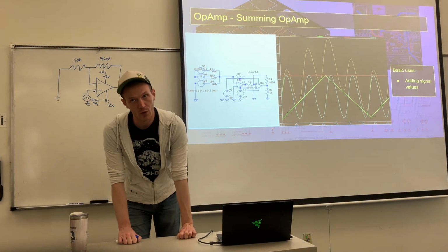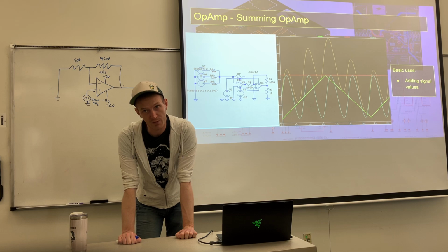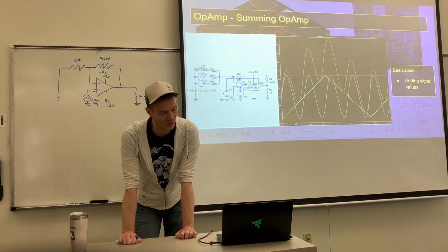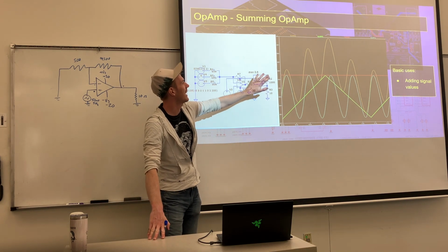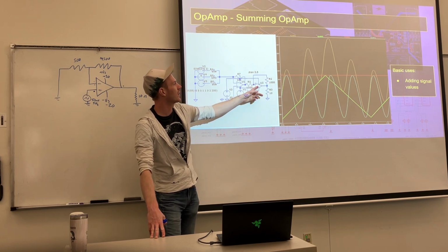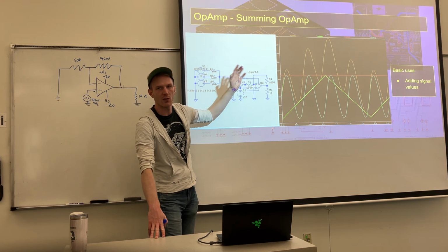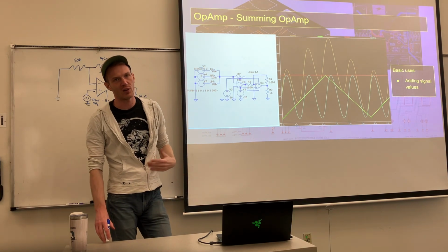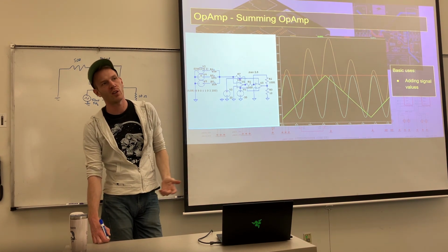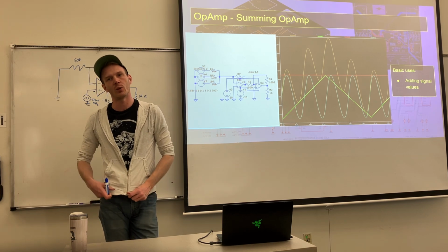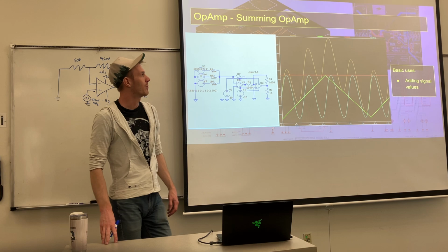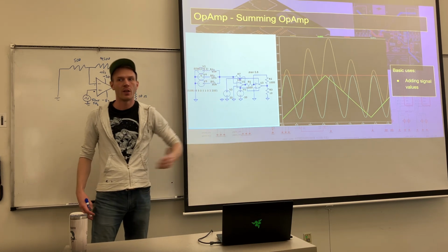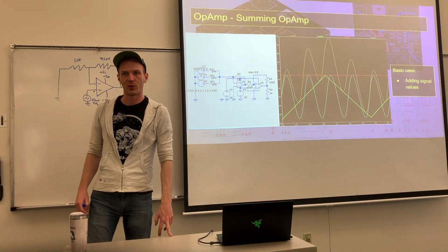They're called operational amplifiers because they do mathematical operations. This is one of the easier ones to do. And this second op-amp, you just kind of ignore. This is literally just here to make it positive. If you look at most of these operational amplifier configurations, almost all of them invert the signal while they're doing it, and I didn't want to have that for this one, at least the first one, because it would just make it more difficult on us. But this is a summing op-amp. This does basic addition for us.